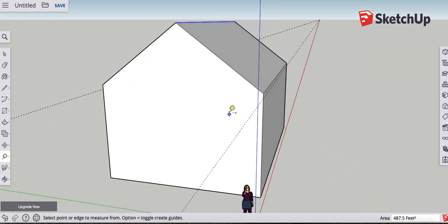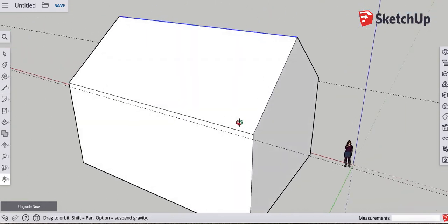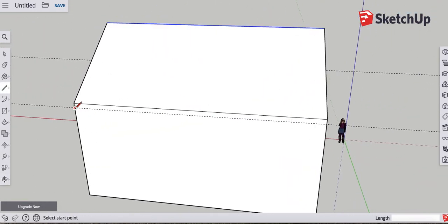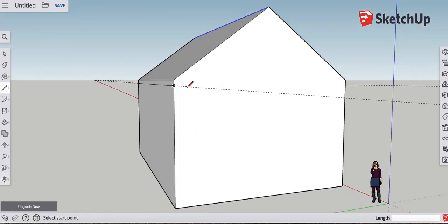Okay, so I have these construction lines now, where what I'll do, with my Line tool, is actually draw a real line going across here. Orbit around by holding your scroll wheel. Remember that you can also orbit by clicking on this tool here. Okay, so I've drawn those lines. Perfect. Next though, I want to draw the lines going up here as well.